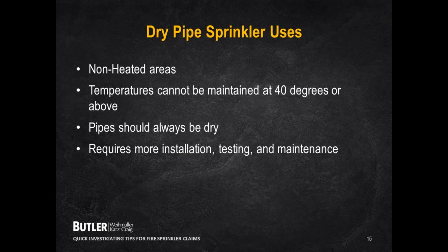If you have a freeze and a break in a dry pipe, that's bad, because there should be no water in it at all. And as a result of the air pressure in the dry pipe, it creates condensation and builds up moisture inside, which permits corrosion over a period of time.